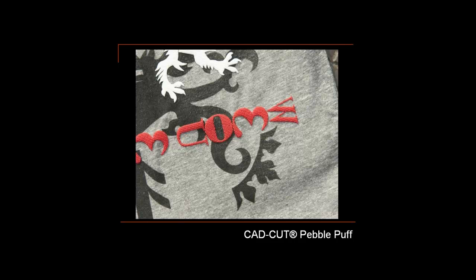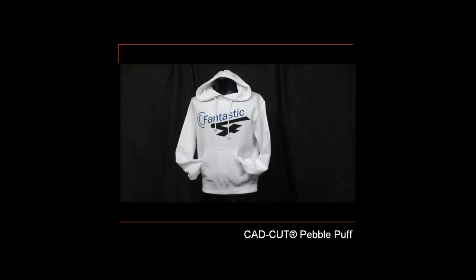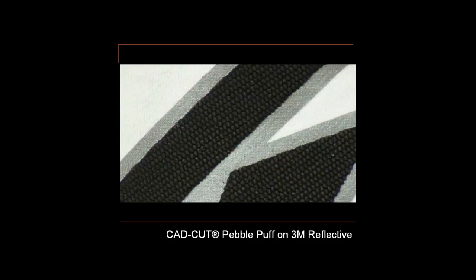This material starts flat. You utilize the same workflow: cut it, weed it, heat apply it. And in the heat application phase, you're just going to rest the press against the material for 20 seconds, and these puff capsules explode and give you this really nice dimensional look on the garment that's almost like high-density screen printing. I think this product does really well on fleece garments and hoodies that I'm showing it here on. And there's a super close-up shot of utilizing the pebble puff on top of 3M reflective.